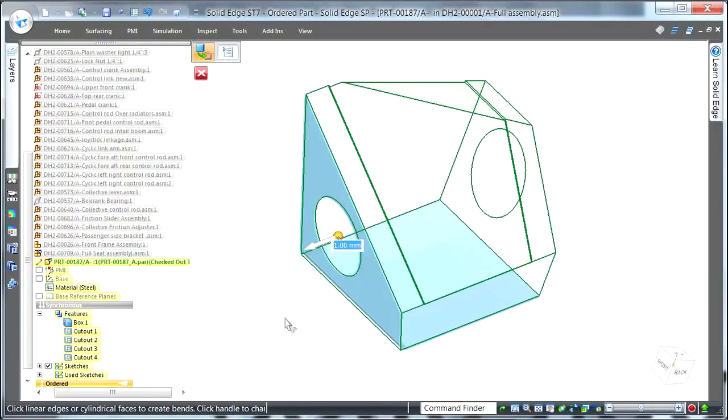So obviously we've modeled to the outer extent. We don't want to add sheet metal on top of that. We want it to be inside. So really we're folding sheet metal inside the solid block. Solid Edge is automatically ripping those edges that need to be ripped for us. This is all blue in preview.